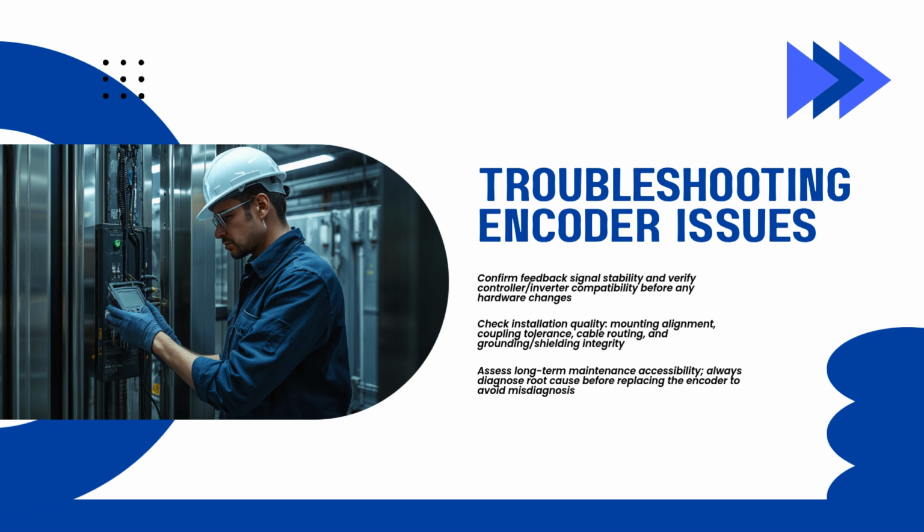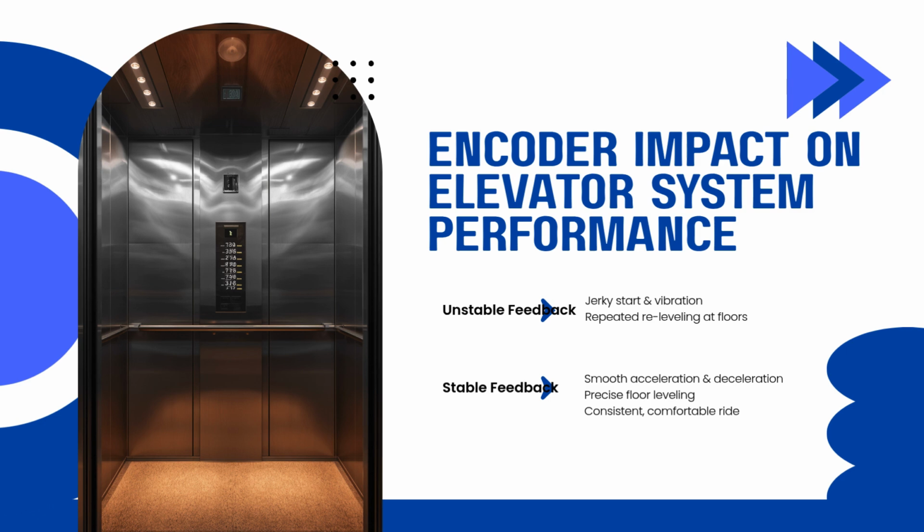Small issues such as coupling tolerance, grounding noise, shaft vibration, cable routing problems, or signal interference can affect the whole motion control loop. Common encoder types. There are several types of elevator encoders. Incremental encoders generate pulse signals based on movement. They are commonly used in standard traction elevators and speed feedback systems. Absolute encoders maintain unique position data, even after power loss. They are often preferred in high-rise elevators, PM motor systems, and advanced leveling control.